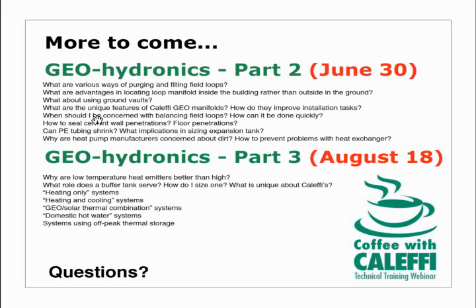One more, let's do. What's typical for a typical 4-ton GEO unit using an open loop connected to the closed loop? Sizing the heat exchanger. I think that would be something the heat exchanger manufacturer would want to know, flow rates and temperatures on that. And I know there are some online calculators available for that.